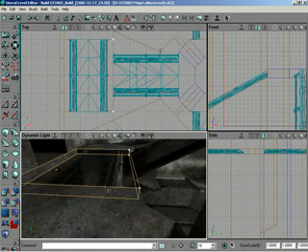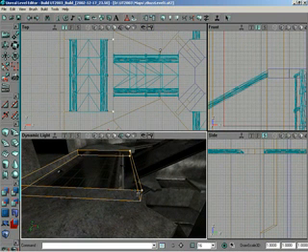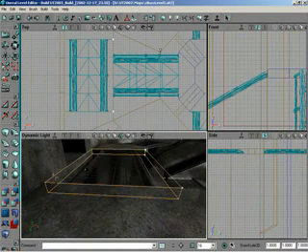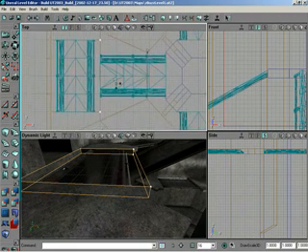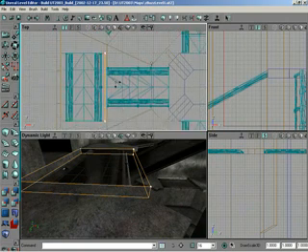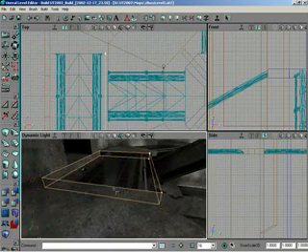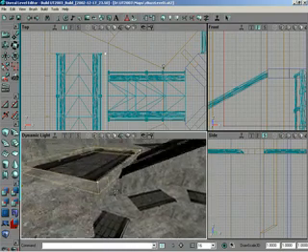Now, if you wanted to actually recreate this brush, the long ways width is 512, and the width this way is right now 384. If you wanted to size it in so you'd have 16 units on the edge, I would make this about 368 units wide, and then move it even with this wall, and you'll be left with a 16 unit bar across here. For the sake of time, we're going to see how well vertex editing works. It'll work great. So pull that in, and just to get a quick view, let me do geometry only. And there you've got a bar that connects to it. Okay.